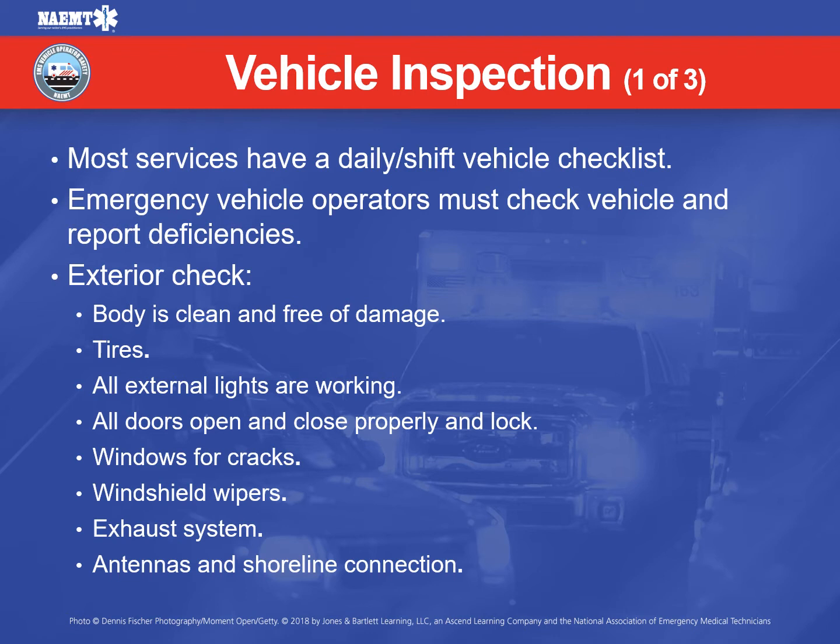You also need to check that all doors open and close properly and lock. Examine the windows for cleanliness and cracks. Check the windshield wipers to make sure they're intact and not worn, and check the exhaust system to ensure that there's no leaks.